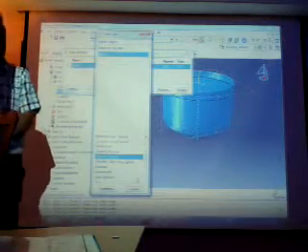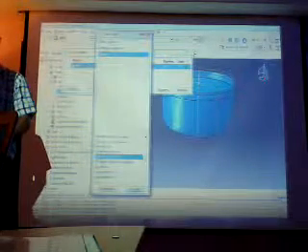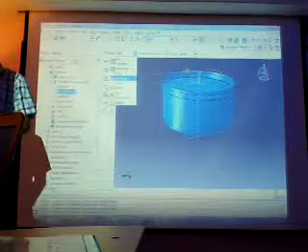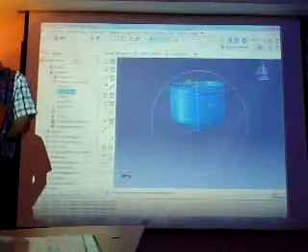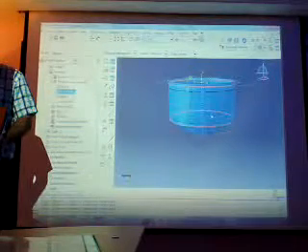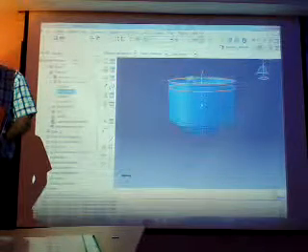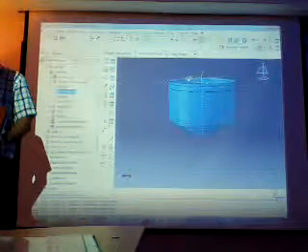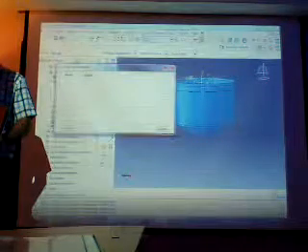So for interaction, let's go to interaction, because this is the most difficult step. The interaction and the assembly and assign. We have three parts here. Interaction between billet and die, interaction between billet and punch. Because punch and die are discrete rigid, we don't need to define any interaction between punch and die. Here I am going to create my first interaction.